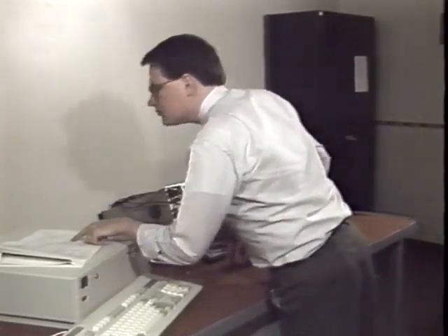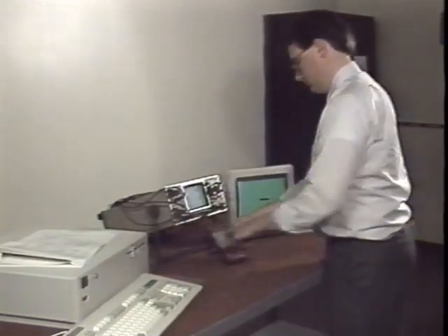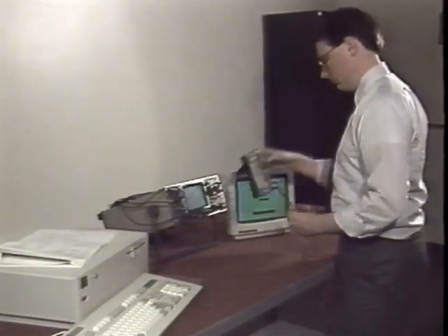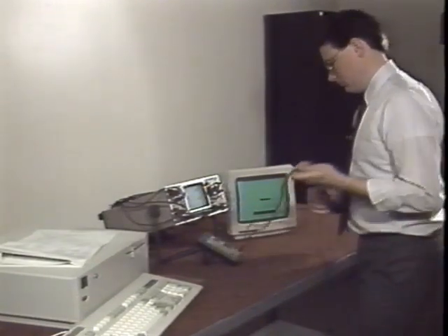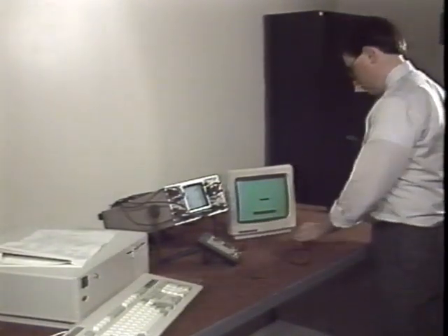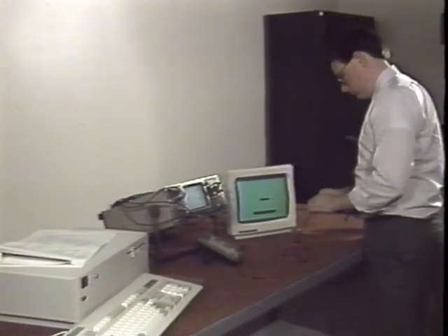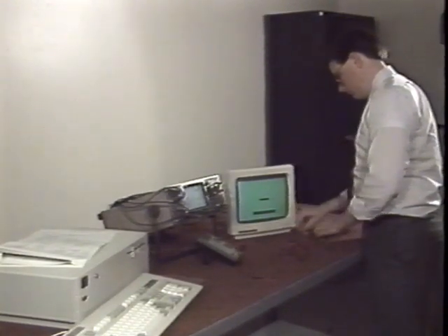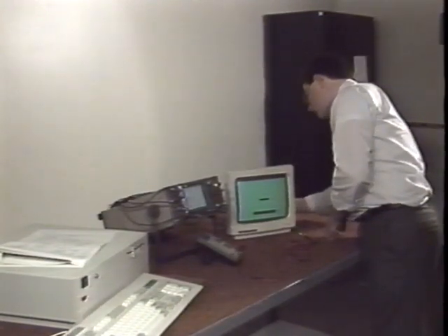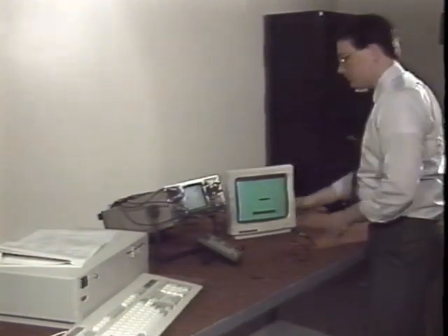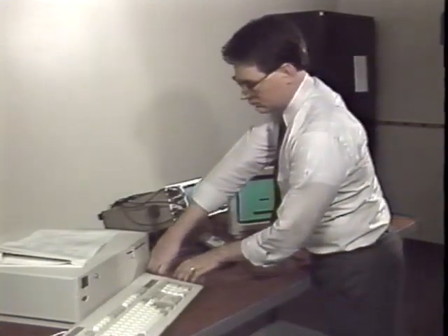Be sure that it is set to read DC volts and that the voltage range is higher than the specified power supply voltage. Select your ground point carefully. In many monitor power supplies, the chassis is not an appropriate ground for the primary side of the power supply. Using an improper ground point can result in a misadjusted power supply and also in damage to the driver board components in the monitors with hot chassis.